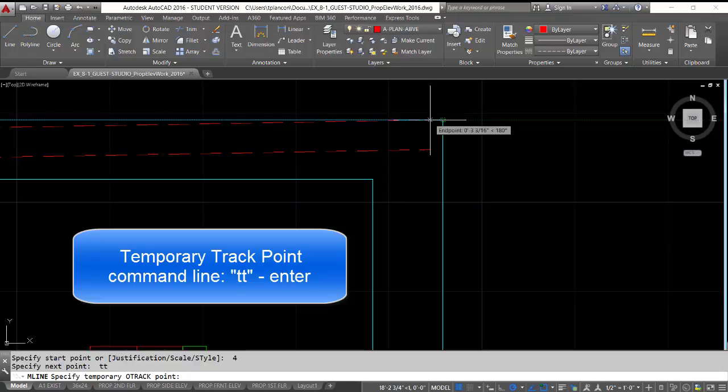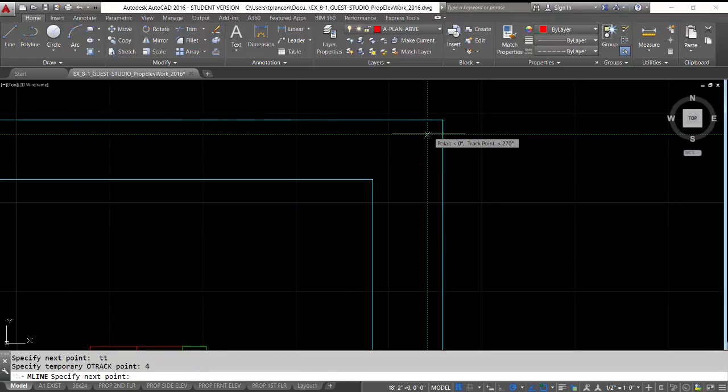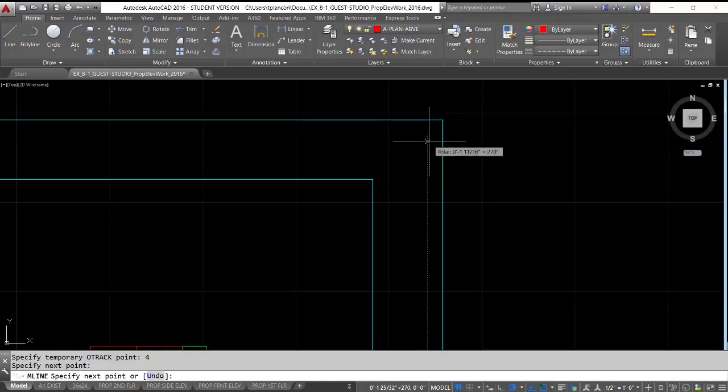It's 4 inches over to the left, type in 4, hit enter, and now there's our point 4 inches over. I just need to come down and intersect the drag line from the M line, which is already 4 inches down. So click there, and now start heading down.